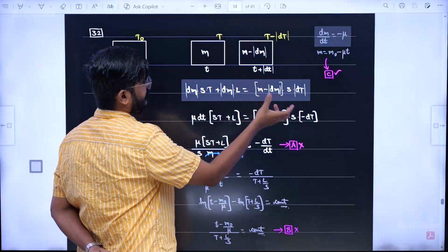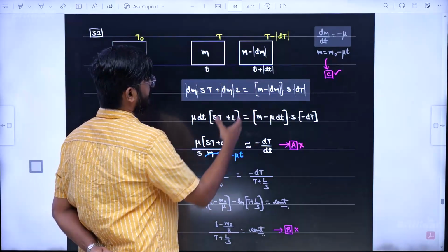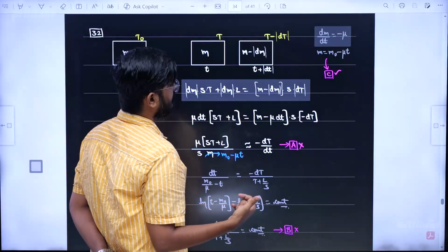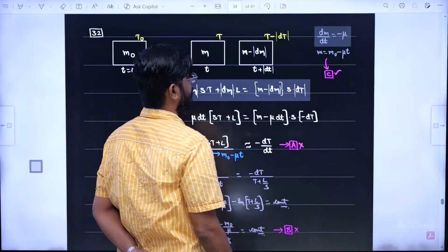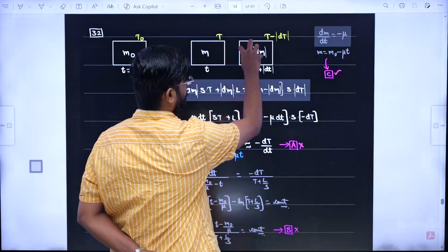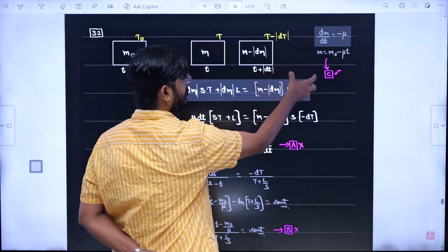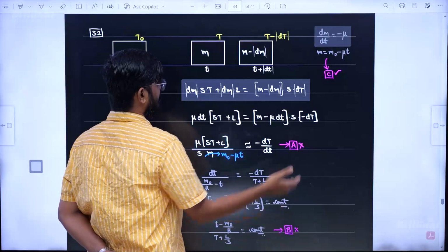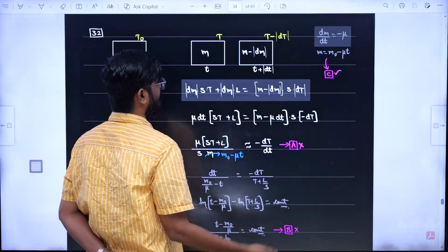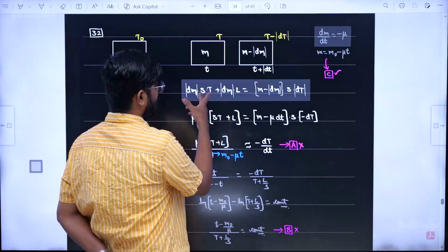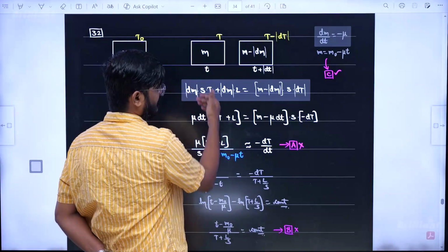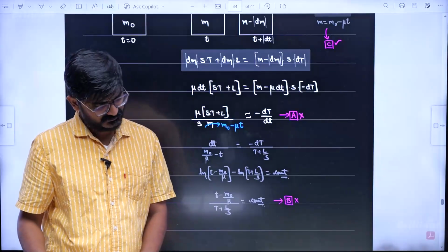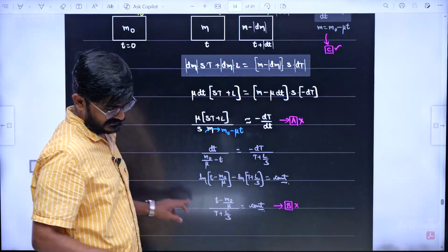Then from there, the energy needed for evaporation is this much, which was given by the rest of the mass available, which was this much. So its temperature is going to reduce by dt. The energy given by whatever is available will be taken by whatever is going as evaporation. This should be 100 minus T. Then the integration doesn't look the same because they didn't consider this factor. So our answer doesn't match with their answer because they were not considering that.